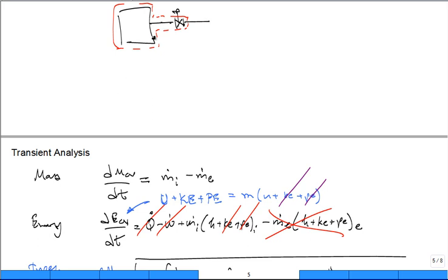What I need to do somehow is to keep what's leaving constant. So maybe I keep the pressure constant, or maybe I keep the temperature constant. It's different wording of problems. Often they do it by putting a little heat transfer into the system. And they maybe dump a little heat early on, but then as it's starting to deplete, they curtail it or speed it up, put more heat in so that the pressure or the temperature stays constant in that tank. You just have to solve these problems.